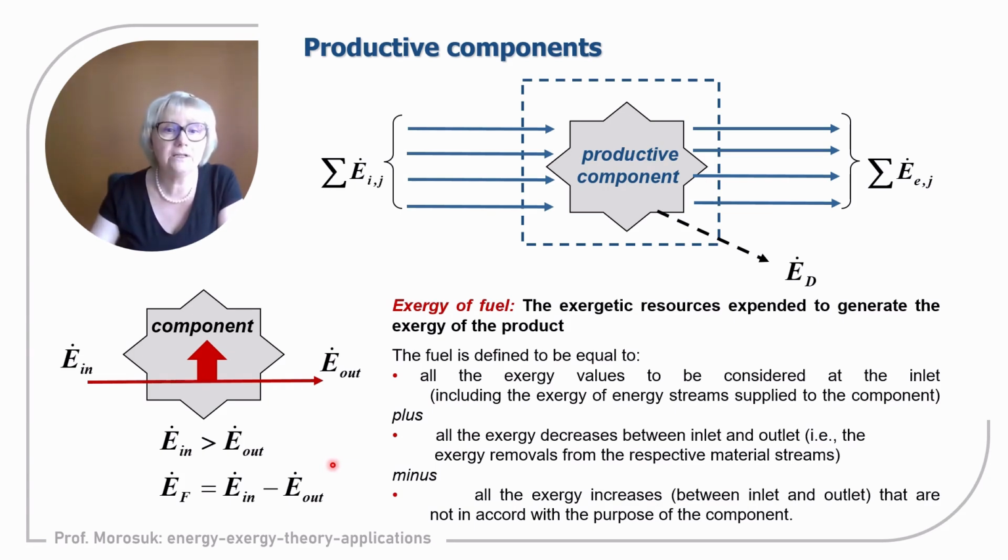And we can already see that fuel is not only the incoming stream; it is the difference between the exergy of the same material stream or energy stream, incoming minus outgoing. This will be the fuel. There is an interesting case: a stream is only coming to the component and after that disappearing.